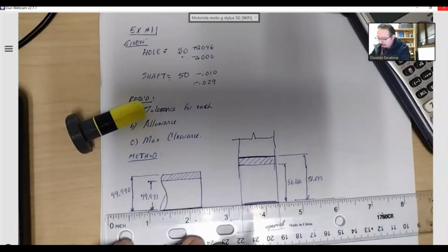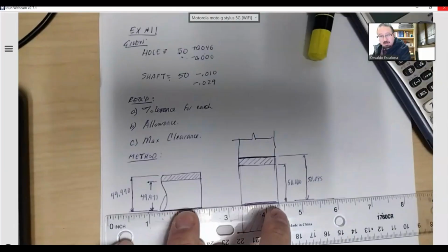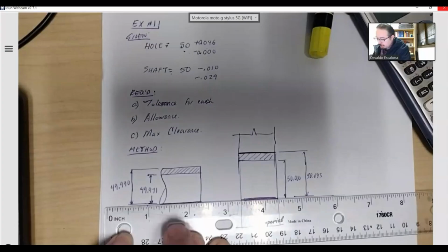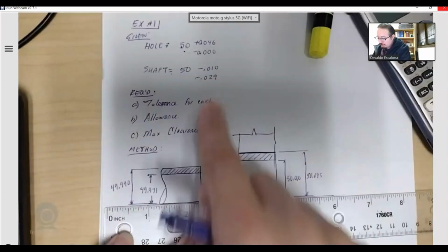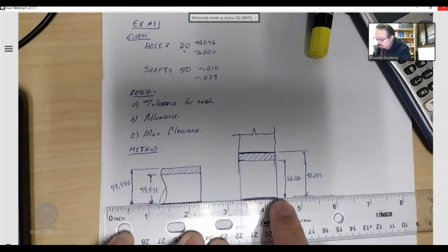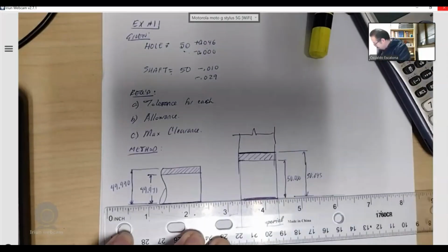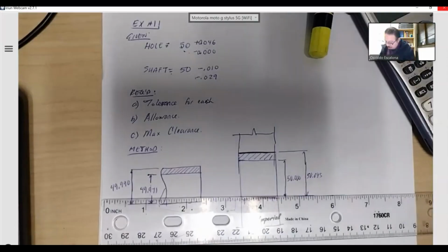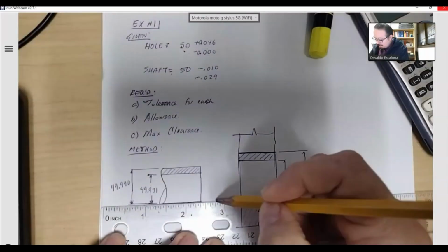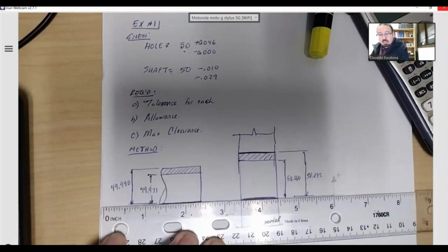The bottom of the hole, the bottom of the pin, I'm representing this to be like the base, like the 0,0. As I keep on going upwards, I keep on getting bigger. Okay. The pin was given to me as 49.971 and 49.990. The hole was given to me as 50 and 50.045. The only reason why I can draw it the way it will look is because I understand that if I continue going upwards, I am going to be increasing the size.